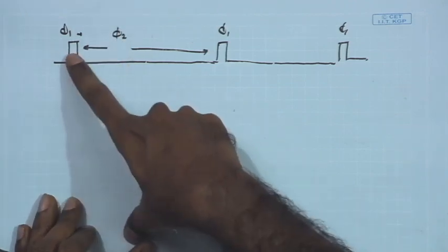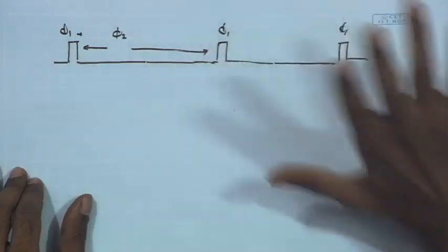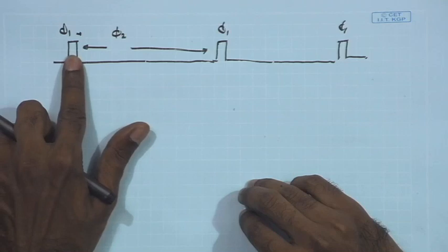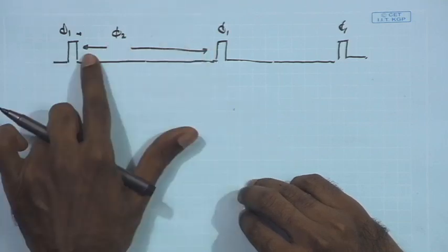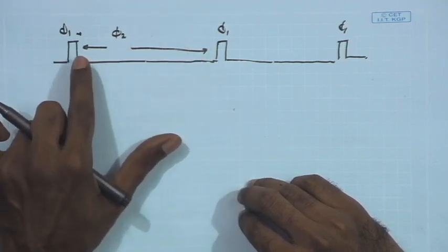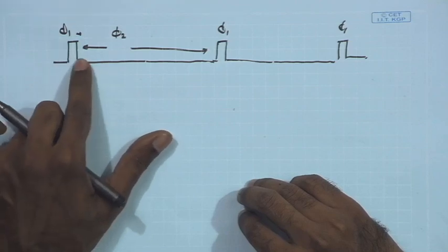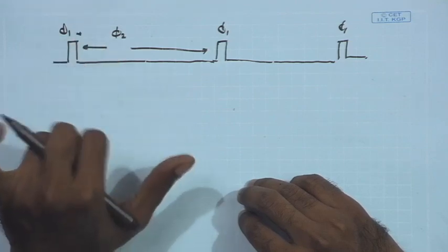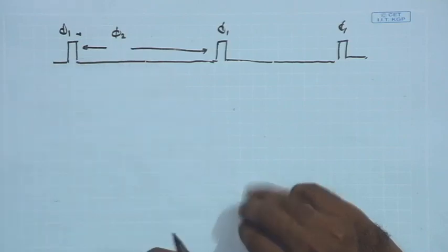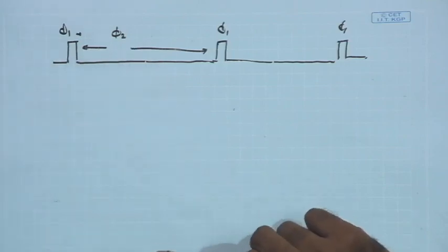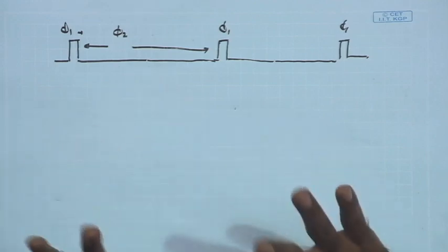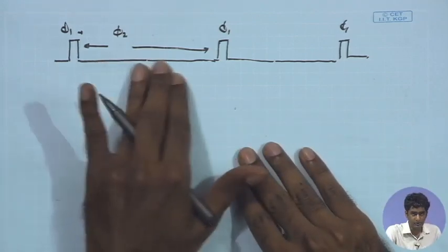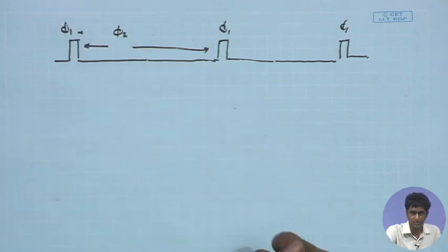Remember, during phi 1 we are sampling the data, and at the same time we are doing the offset cancellation, or the offset sampling, of the comparator. The data is sampled and the offset of the comparator is sampled, and in the phi 2 phase the comparator operation is initiated. So, the ramp circuit starts charging the capacitor, the voltage starts rising, and the counter also starts counting. So, at the core of it, of course, we have a counter at hand, with the help of which we are going to implement this overall operation.